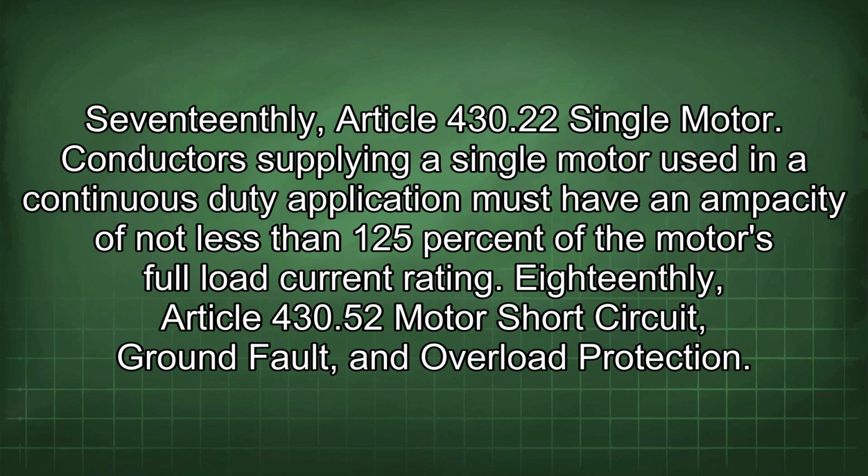Seventeenth, Article 430.22 Single motor. Conductors supplying a single motor used in a continuous duty application must have an ampacity of not less than 125% of the motor's full load current rating.